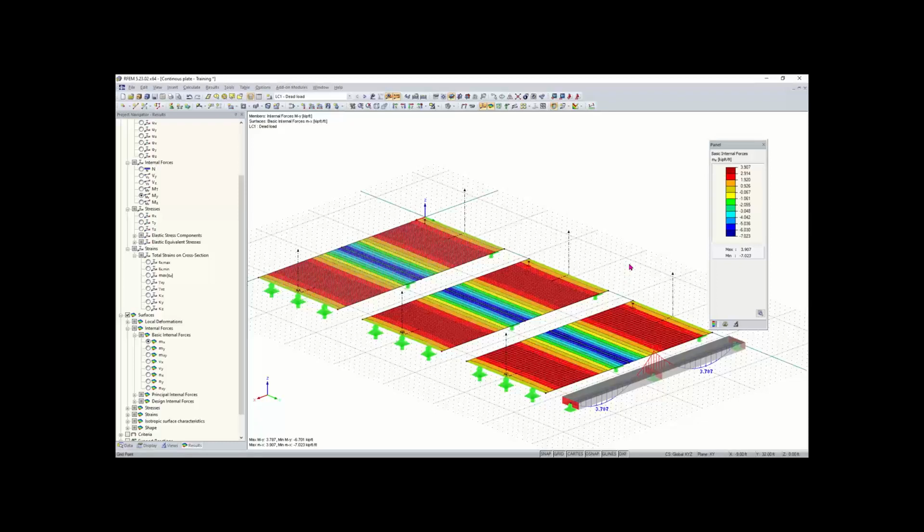Yeah, I think exactly as Alex had mentioned, it's basically just running a test and trial type process where you continue to decrease the FE mesh size. And as he says, if your results are changing significantly, then you know your FE mesh is not refined enough. The other thing I wanted to point out, if Alex, you can go to calculate FE mesh